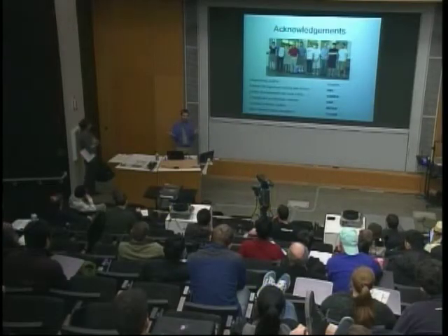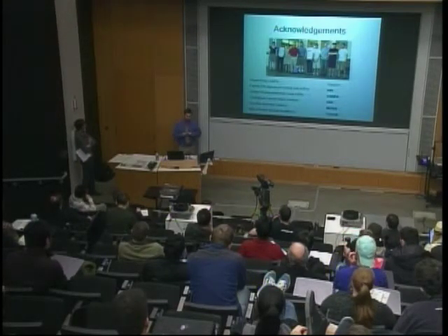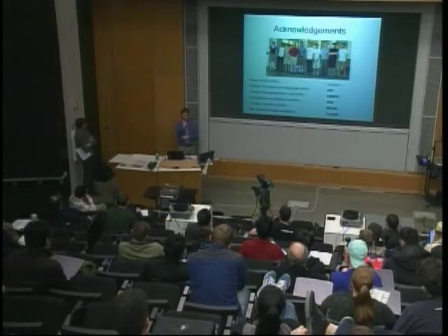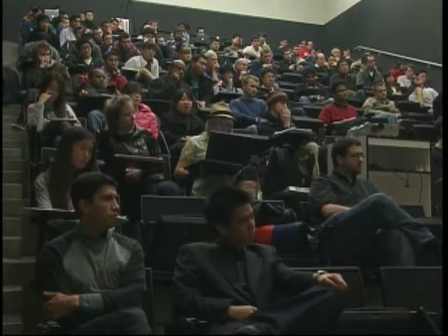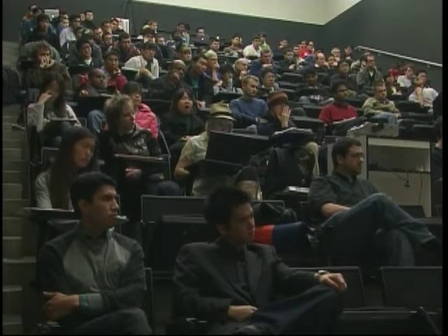And basically, your resolution is set by sort of reversing classical sampling theory. Your resolution is set by your highest frequency capture. And the way you get higher frequency is by either making the gratings finer, but at some point you hit wavelength and you can't go finer. So you can't go below about 2 lambda and it starts not working. Or making them farther up, so just basically separating them by more.